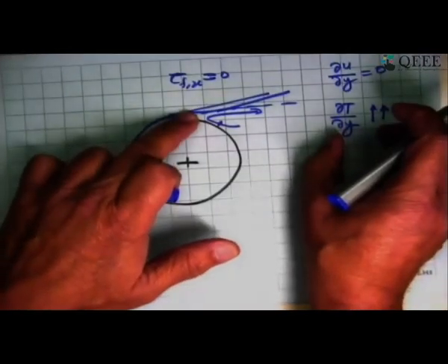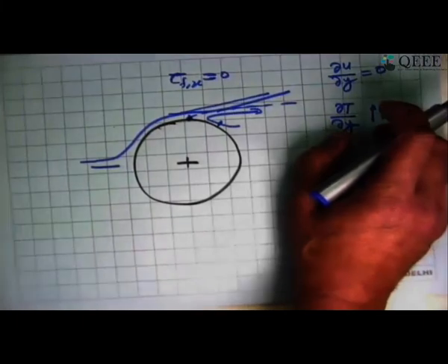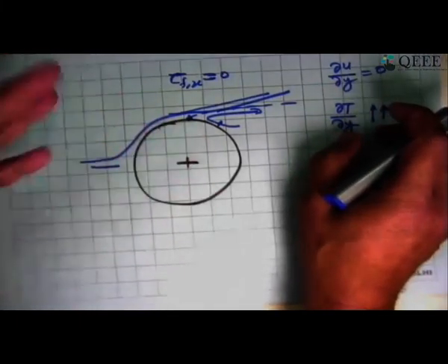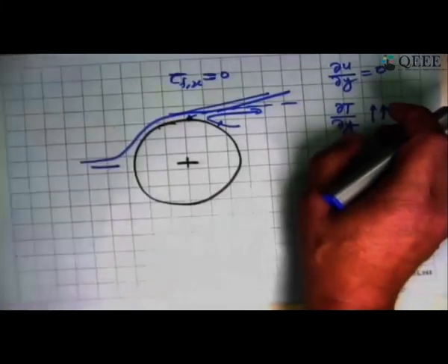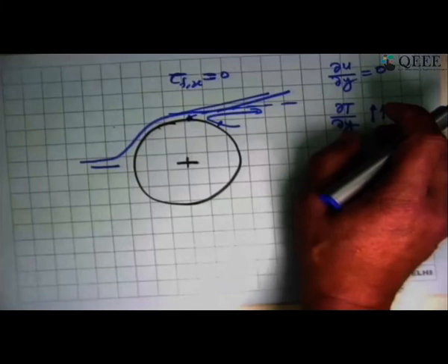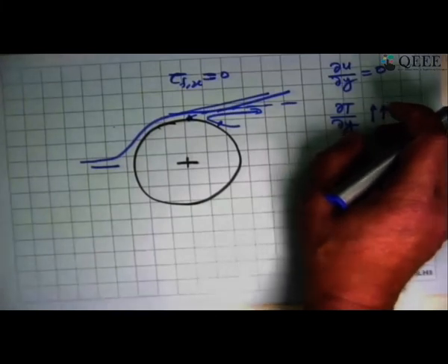Yes. So in that sense, for Prandtl number close to 1, which is say water and air, which is what we're looking at, this will happen: where the hydrodynamic separation takes place, you will experience a very low heat transfer coefficient at that point. Okay. Yeah. Any other questions? Okay.